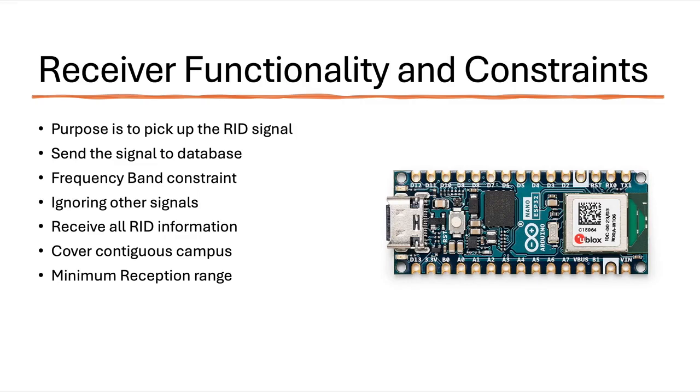We're doing this because, with the 5.8 gigahertz signal, we would have to increase the number of receivers to be able to pick up the signal, because its range is not going to go as far. The signal is not going to travel as far, so we're going to need more receivers to cover more area so we can pick up that signal, when the 2.4 is already going to go further anyway, and that one has to be emitted.